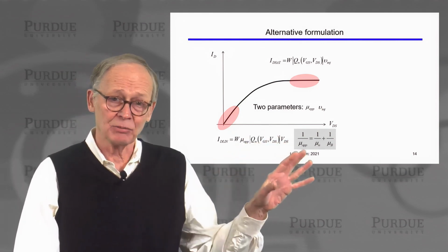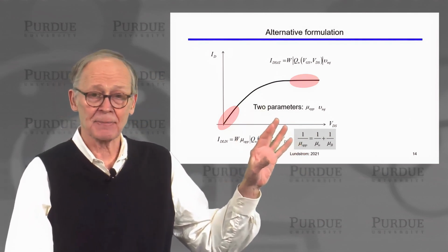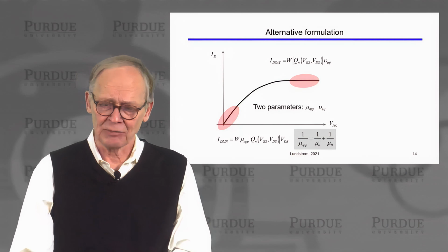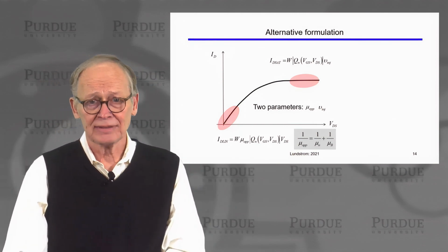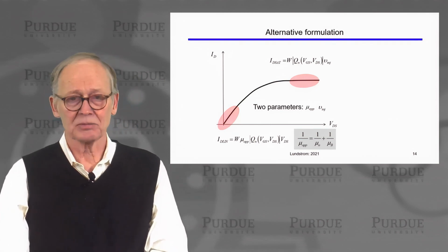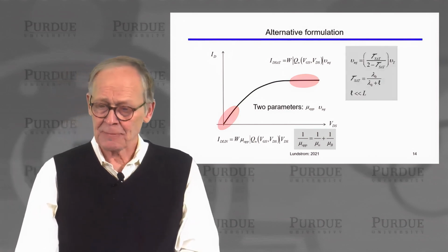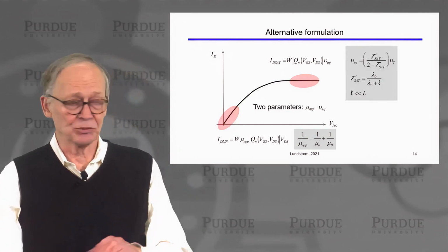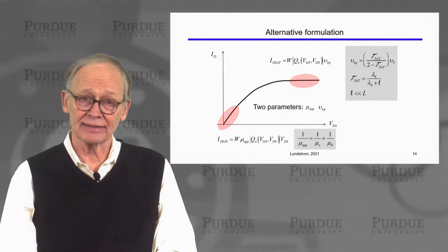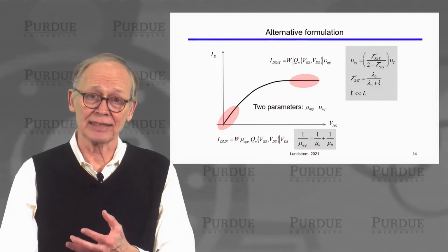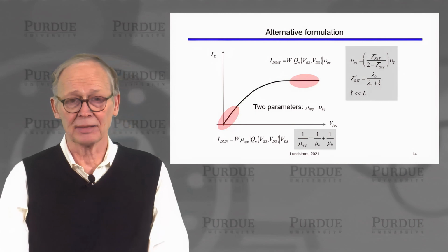The apparent mobility is the lower of the actual scattering limited mobility and the ballistic mobility. And remember that the ballistic mobility is proportional to the channel length. So as the channel length gets shorter and shorter, it's the ballistic mobility that's going to dominate. The injection velocity is related to the transmission, and the injection velocity is always less than the unidirectional thermal velocity because the backscattering causes some negative velocity electrons to be apparent there.